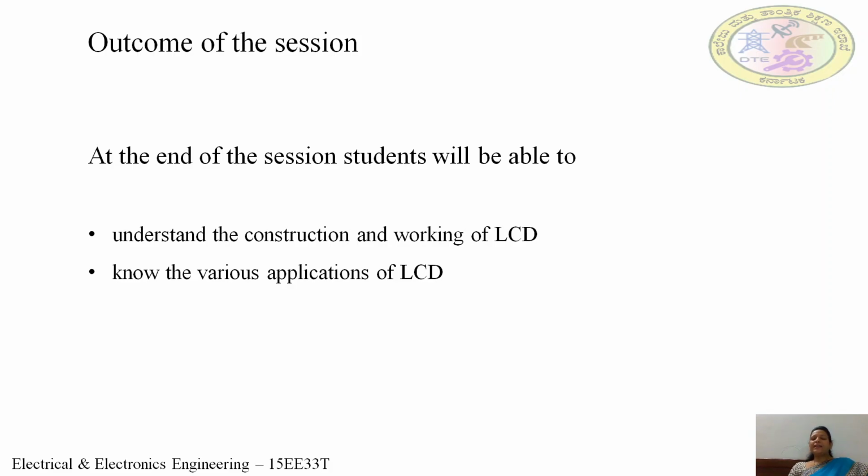And the liquid crystal has a natural twisting of molecules up to an extent of almost 90 degrees. So on one side the molecular arrangement is almost vertical. On the other side of the liquid crystal, the molecular alignment is almost horizontal. So on one end of the liquid crystal where the molecules are vertically aligned, we have a vertical polarizer. On the other side where the molecules are aligned horizontally, we have a horizontal polarizer.